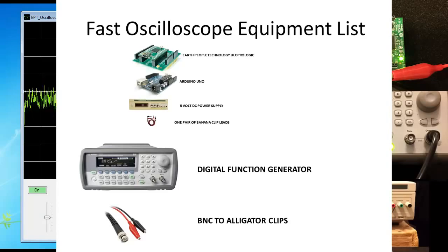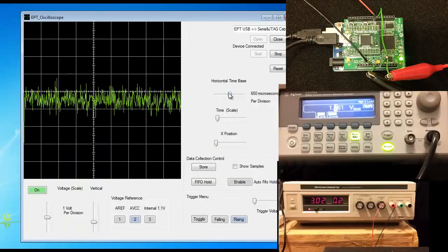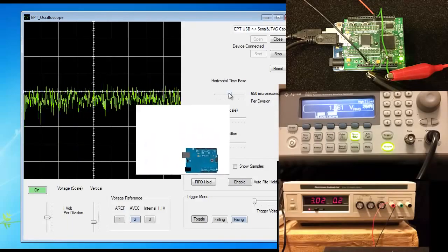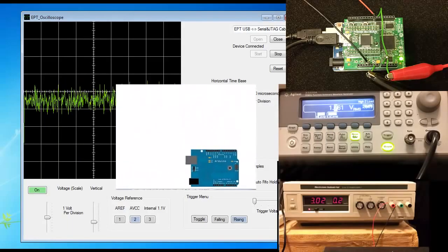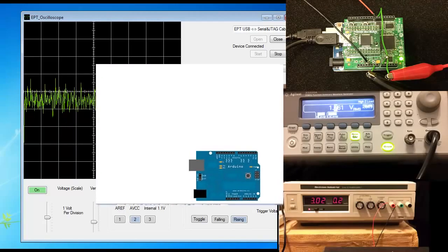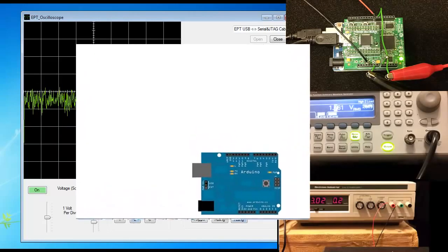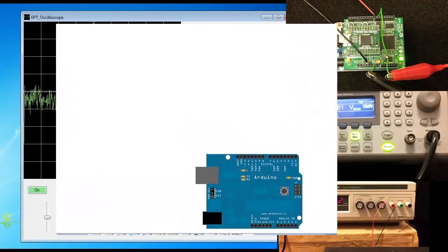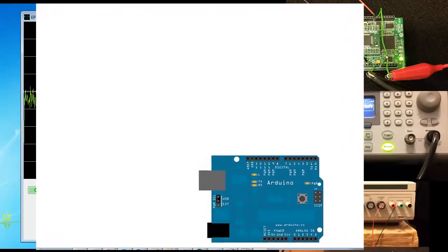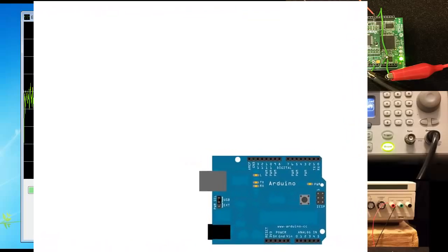Next up is a description of the hardware needed for the oscilloscope. The Arduino uses the analog comparator to trigger the scope. The ADC then samples the analog channel 0. The samples are stored in a buffer in the SRAM. Because of the method of using the Arduino hardware to behave as an oscilloscope, we have to build some hardware. The analog signal must be applied to both the analog channel 0 and the input to the analog comparator.